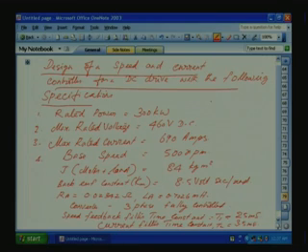Okay. Let us say our maximum current is 690 amperes, and our maximum current limit is equal to 1200 amperes. So, this is the maximum rated current. For momentary we can give the rated current of 1200. That is the maximum current limit. So, let us first design our current controller.